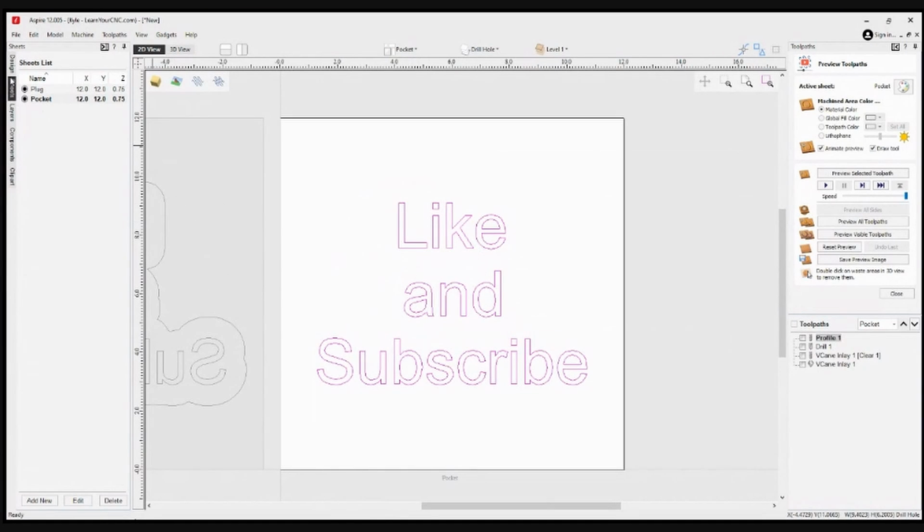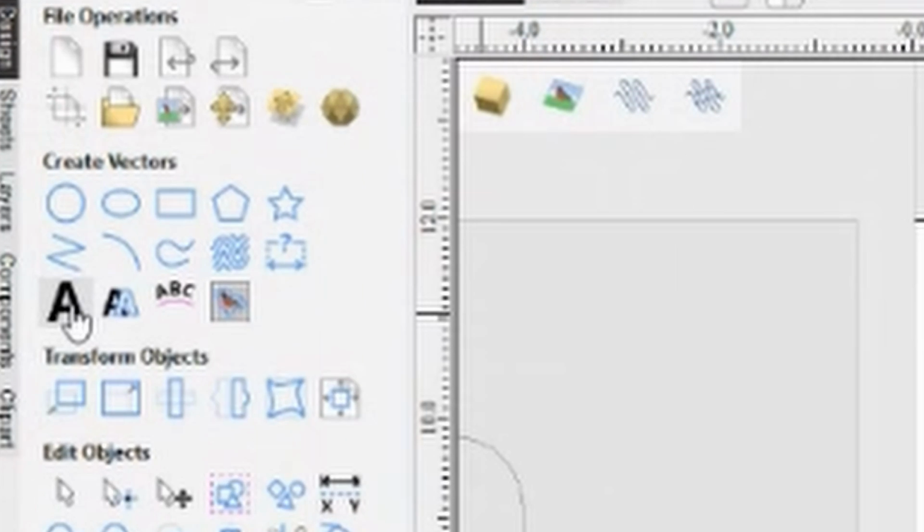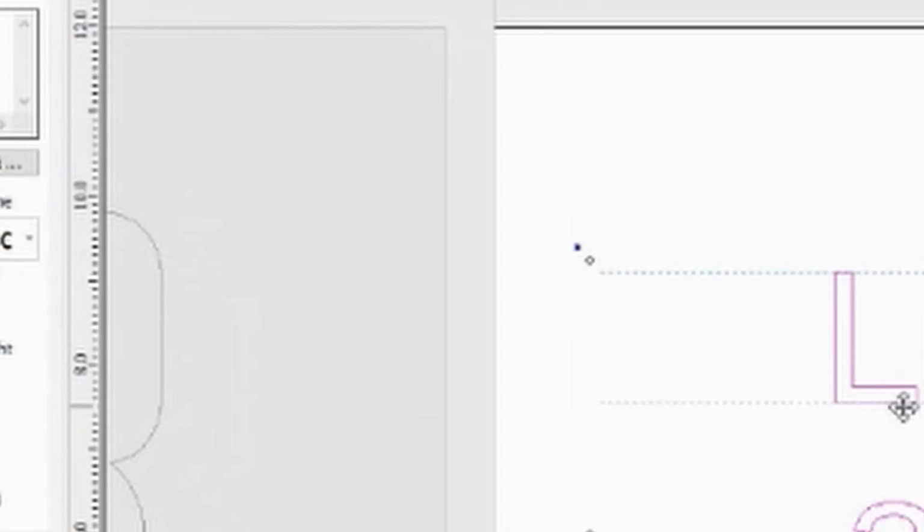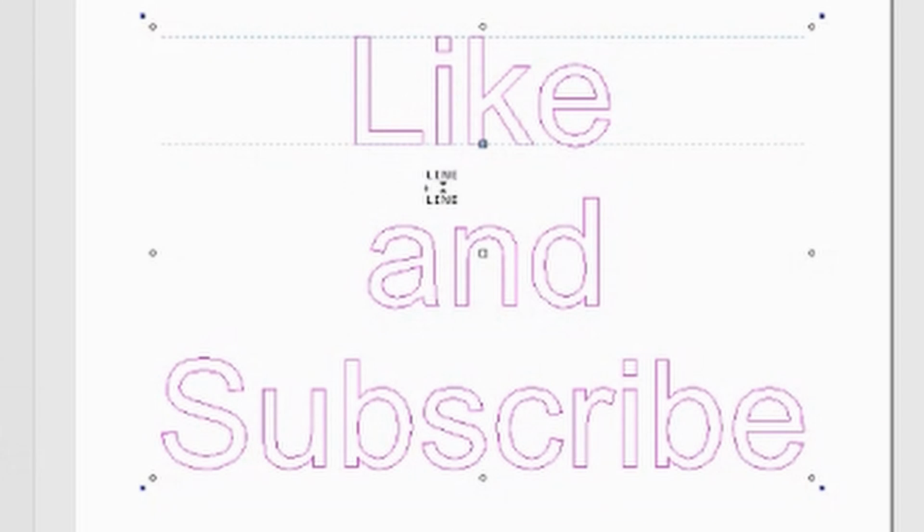So let's go back. Okay, with the text, you're going to be using the draw text tool. And now you have text and text within a box all in one tool. And like I said, if you move your cursor onto the screen, you can click in between the letters to adjust spacing between them. And there are other shortcuts like Control, Alt, and Shift. Those three buttons will all do something different, and if you hold them together, they do different things.